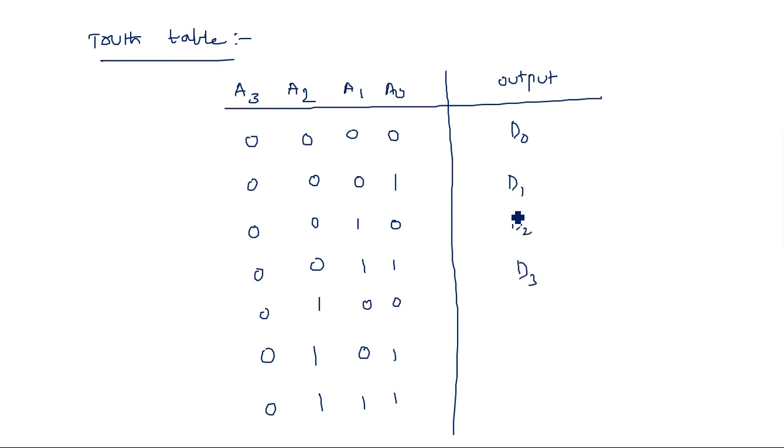What is the meaning of this D0, D1, D2, D3? When 4 zeros are there, you can also take it in the other way, like D0, D1, D2, D3 up to D15, total 16 pins horizontally, and the corresponding output bit is activated by giving 1 and the remaining are all zeros. That is one way of representing, but it takes a longer space. If you take the output as a single column and mention the corresponding bit which is activated, it means the remaining are all zeros.